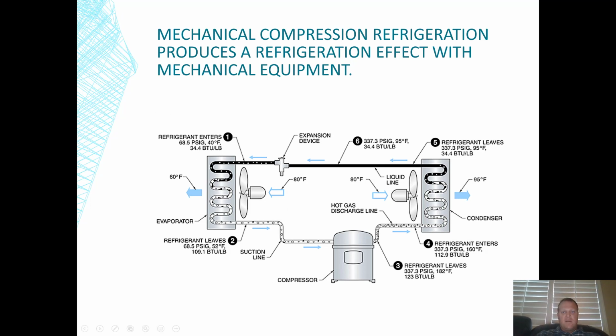So we're talking mechanical compression refrigeration. And if you remember in the past, we talked about this a little bit where we've got the compressor and the condenser, and that's outside, we're just talking at like a residence, a home, right? So the compressor condenser is sitting outside, and there's a little compressor surrounded by a coil, and the compressor compresses a gas refrigerant into high pressure. And as it goes around the coil of the condensing unit, it starts to cool off because air's blowing across it, right?